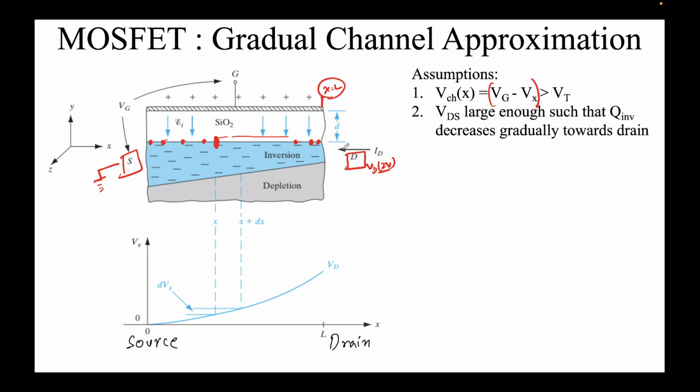On the other hand, on the right side we have the Vd terminal. Now what's happening is that I'll draw it over here. This is our N plus drain, and this is the P. I am applying a positive potential at the drain, and P is grounded. Just look at this N plus P terminal. N plus is connected to some positive potential of, let's say, 2 volts, and P is grounded. This is a reverse bias junction, an N plus P.